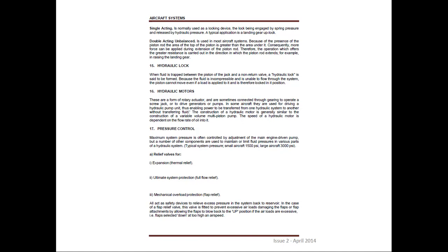If you have seen them crank a propeller, they hold the blade with an open palm and turn it by hand. So what is that for? It is a way to avoid the lock-up of the piston. So that is an example of hydraulic lock, fluid lock, or air lock. I hope you understand what a hydraulic lock is. So, hydraulic motors.